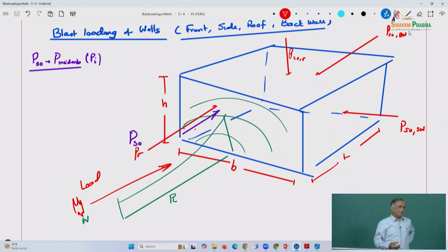And in practical applications, we've tried this with bridges. We've used a standard bridge design software, and those are all static loads, but we have converted these loads into pressures in this manner and applied them, and of course it is much higher, as some kind of a static load. You could add factors. I don't know if there's a whole lot of research, like you have an impact factor in bridges due to dynamic loads. I don't know if there are impact factors for blast, so those are some things that you'll have to account for.